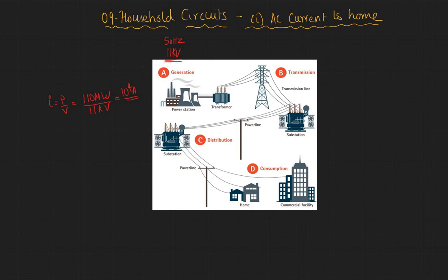Now once this current gets generated at 11 kilovolt, this is stepped up. So this is a step up transformer, and this is stepped up to about 132 kilovolt, and this we call your grid substation. So the grid is a national power line network that passes across various states. We call these the grid lines. Those are about 132 kilovolt.